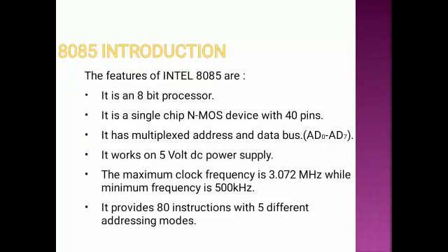It has 8 multiplexed address and data bus. It works on 5-volt DC power supply. Maximum clock frequency is 3.072 MHz. It provides 80 instructions with different addressing modes.